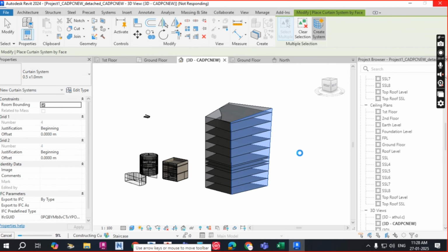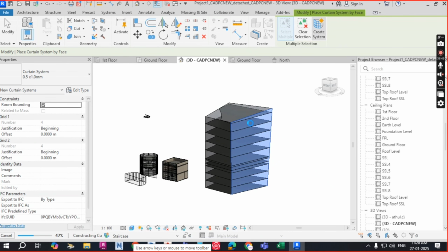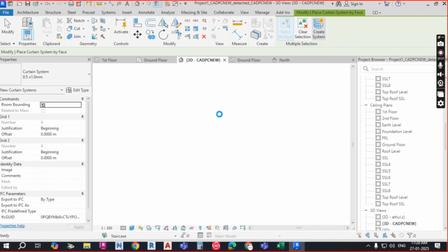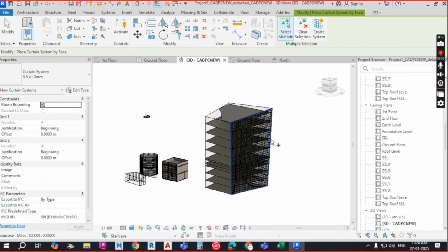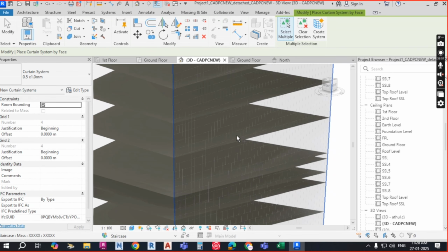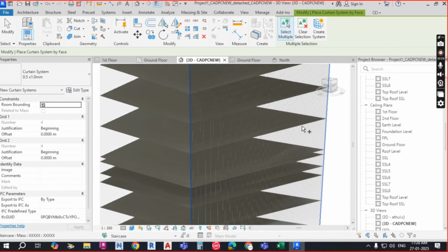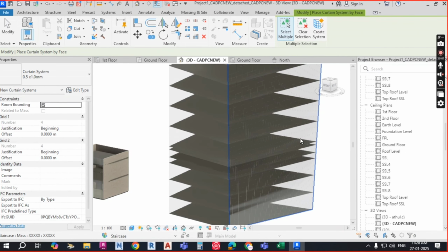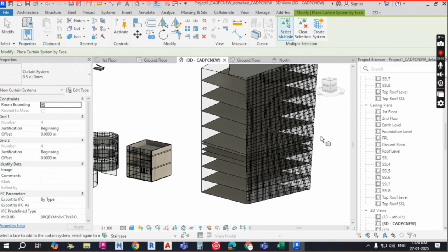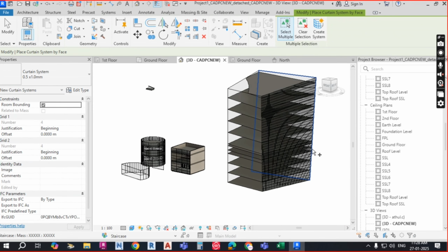So automatically you can see the curtain system has come with this shape automatically. So this is the vertical face, the curtain system is going to be applied. So manual modeling is not required, directly it is giving the model based on the mass body system. It is going to be created, the model. You can see your model has been created, because of the exterior part. You can see this type of towers, this type of buildings you can find outside of any city.